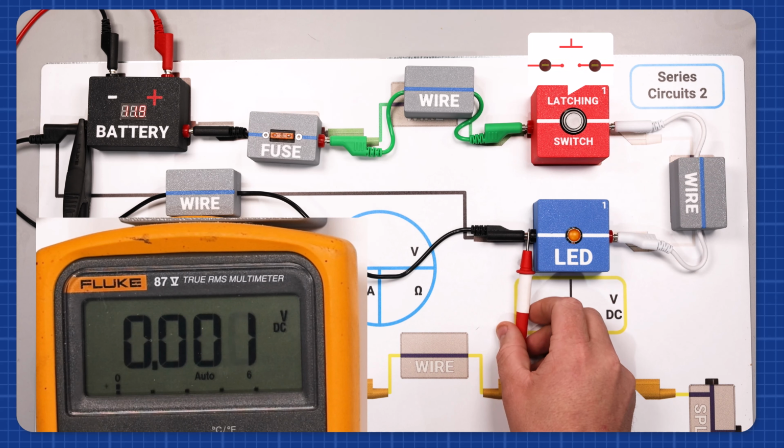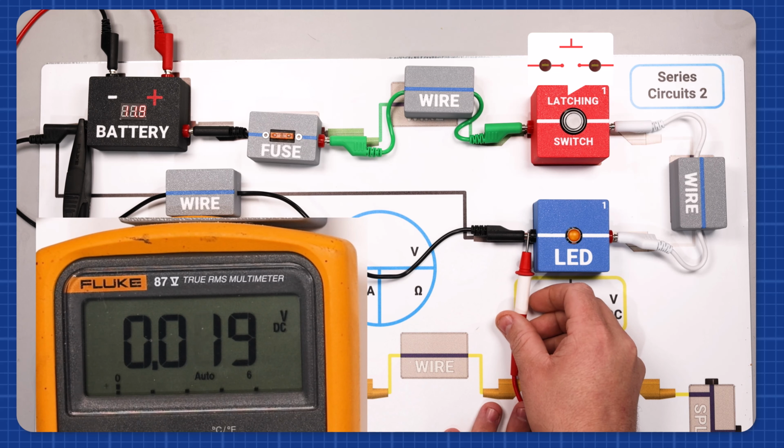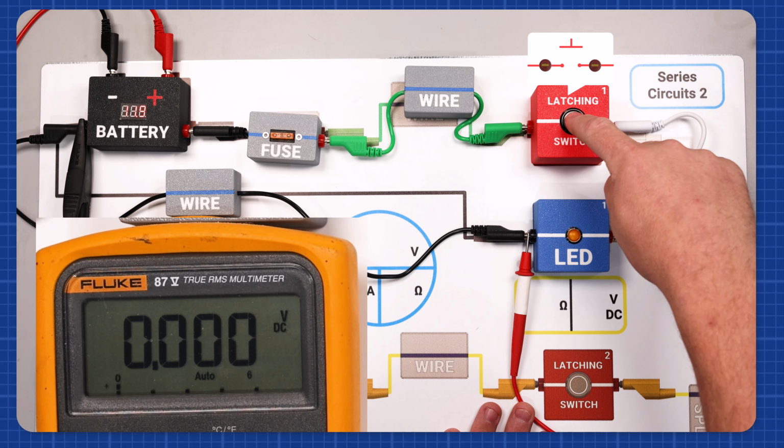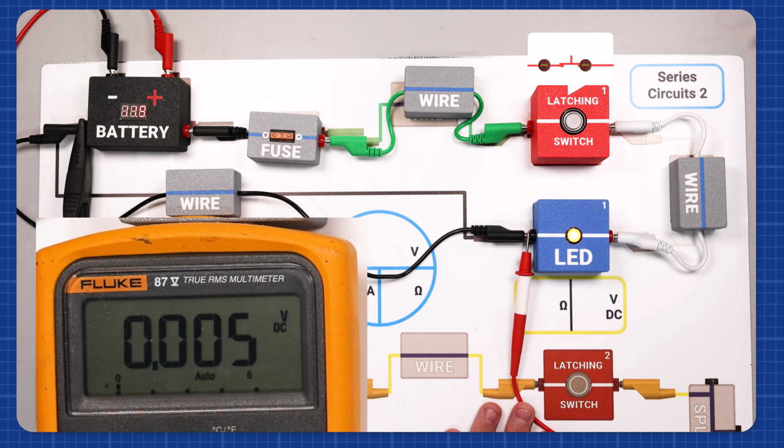Step 6. Measuring the voltage at the ground side of the LED. Finally, we measure the voltage at the ground side of the LED. With the switch open, the voltage remains at 0 volts because no current is flowing and there's no potential difference on this side. When the switch is closed, the voltage on the ground side of the LED is still 0 volts. This is expected as this is a return path to the battery's negative terminal. The potential difference has been fully utilized to power the LED.